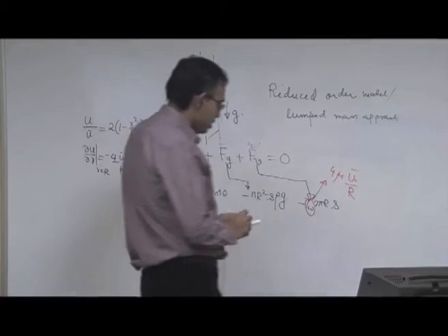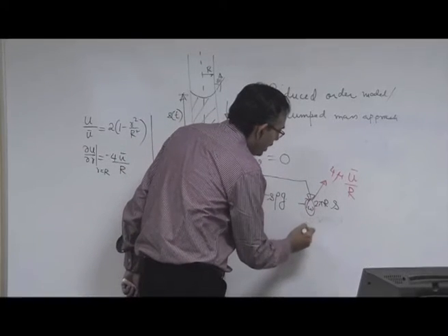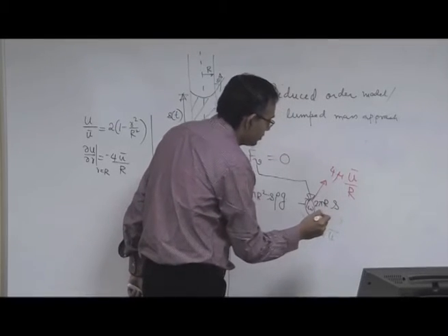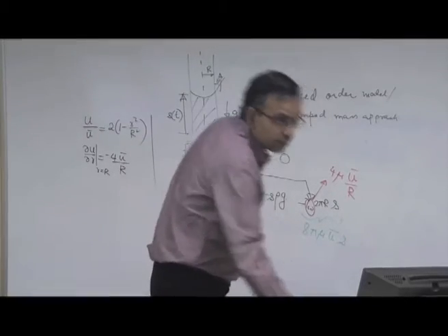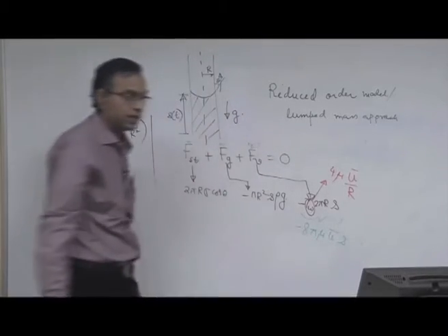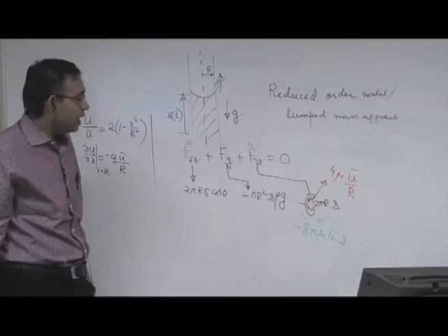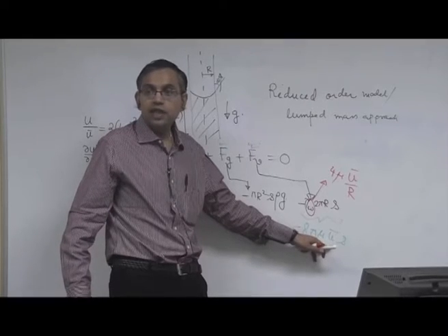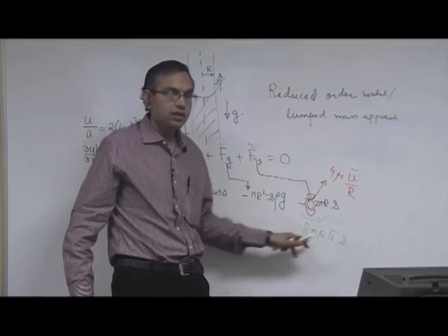So, this expression becomes 8 pi mu u average S, right. Minus, of course, I have excluded the minus sign, so minus is there. Very interestingly, the viscous force has no relationship, no scaling with R. Make R large, small, medium, whatever, this does not change.